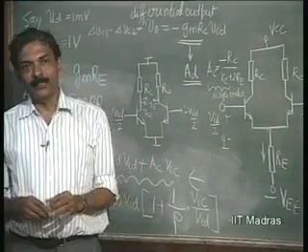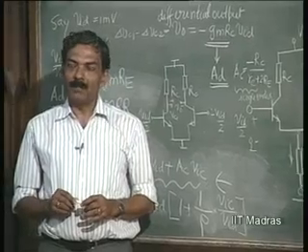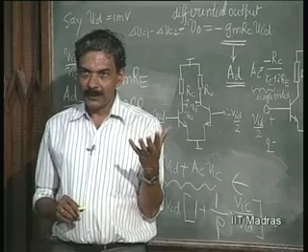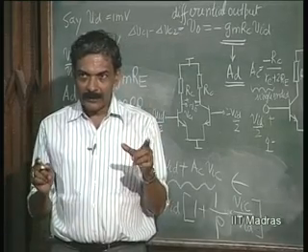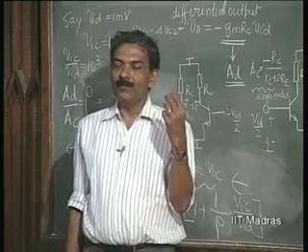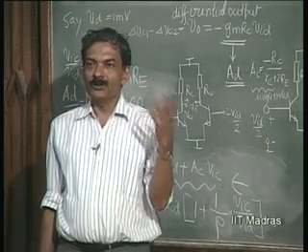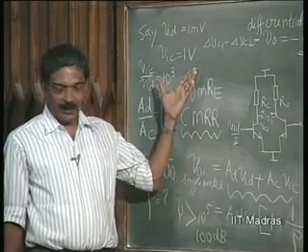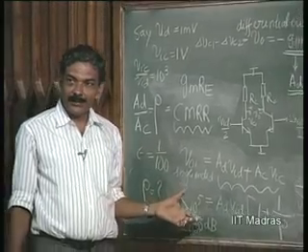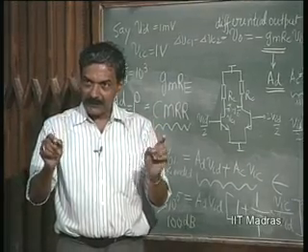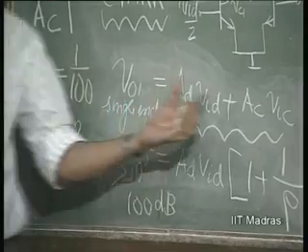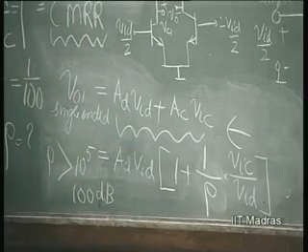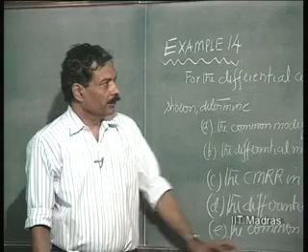For example, a practical commonly encountered problem is your problem of measuring differential voltage in the case of cathode ray oscilloscope. If you want to make measurement, then if you are making measurements of the order of 1 millivolts also, superimposed over 1 volt, which is a typical situation in the case of cathode ray oscilloscope. What kind of common mode rejection ratio your cathode ray oscilloscope differential amplifier which is placed inside should have, in order that error is less than 1% is easily computed from this kind of discussion.